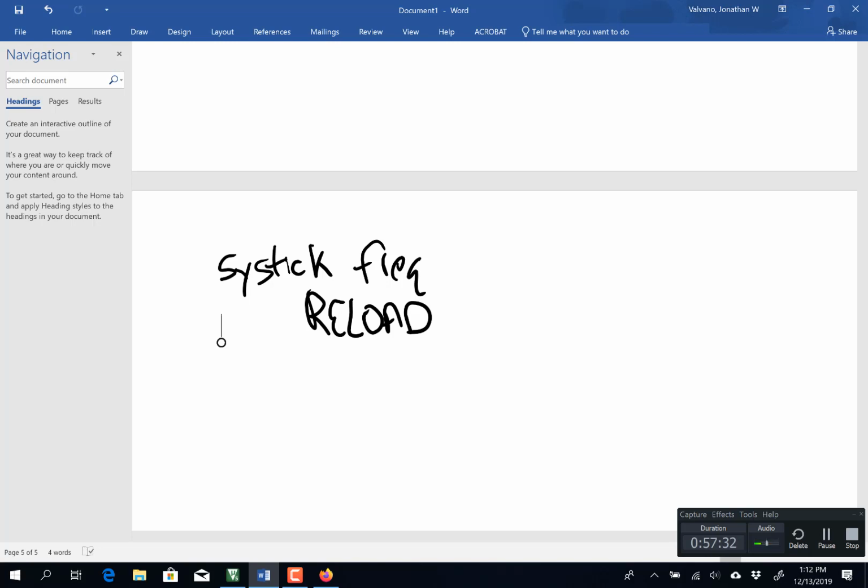Assuming I'm going to generate interrupts, what two things will affect the SysTick interrupt frequency? The reload and the bus clock. Okay, so it goes to reload and counts down to 0, interrupting. The SysTick frequency is going to be the bus frequency divided by reload plus 1.